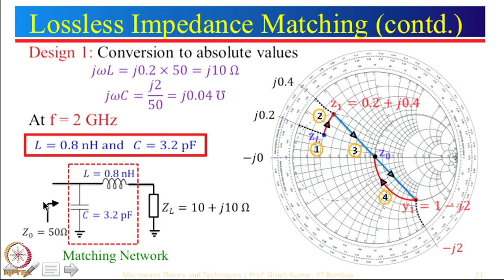Now, this is another concept which a lot of times students ask me. This was the amplifier here. The amplifier now sees a 50 ohm impedance, and this is 50 ohm. So maximum power transfer takes place from here to this particular point, but the load impedance is 10 plus j 10 ohm.